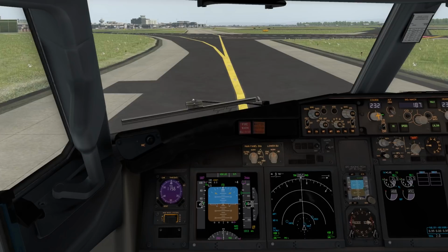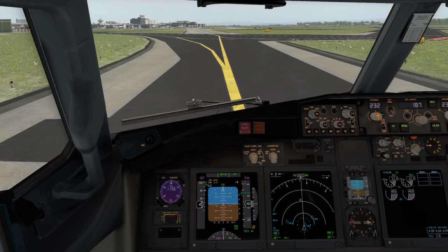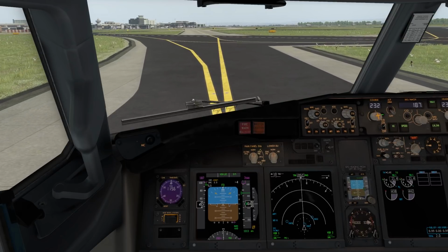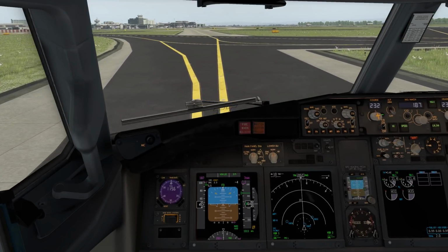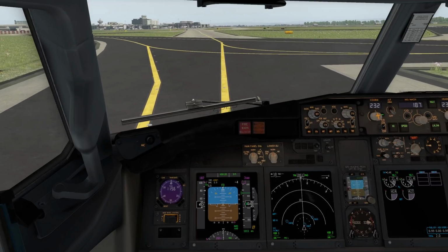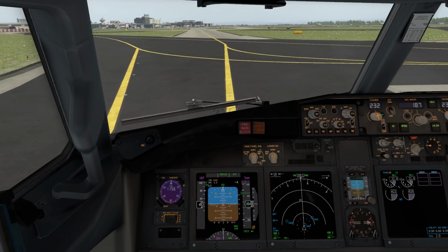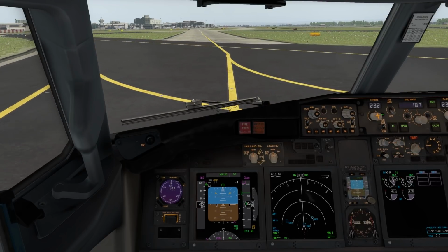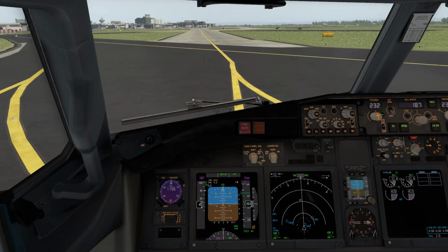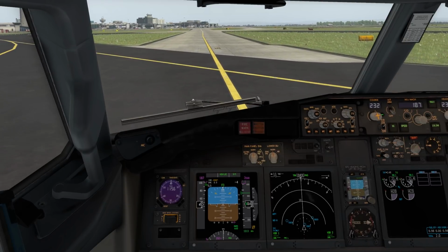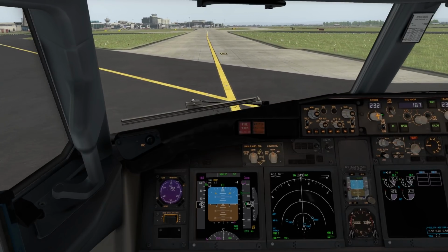Right then guys, that's the end of the all flaps up landing tutorial. I hope you found that interesting and learned something new. As I mentioned earlier, the chances of actually having to do this in real life, extremely remote. You'd not only need a failure of the normal hydraulic system B pressure, which extends the flaps normally, but also the standby hydraulic system for the leading edge devices and the electric motor for the trailing edge flaps. All three failing at once, extremely remote. But the guidance is there in the flight crew training manual, which is what I applied today.